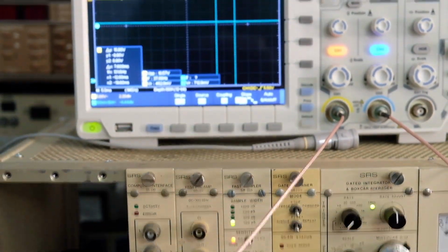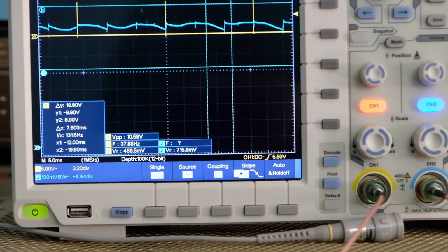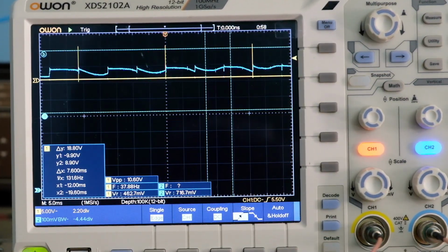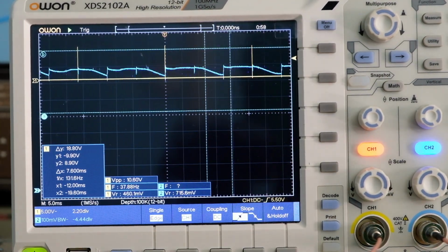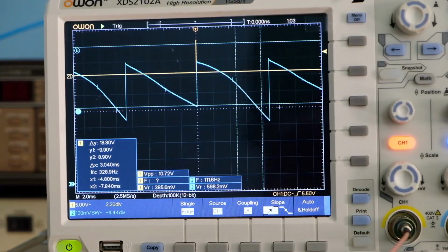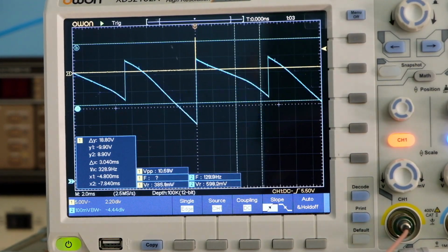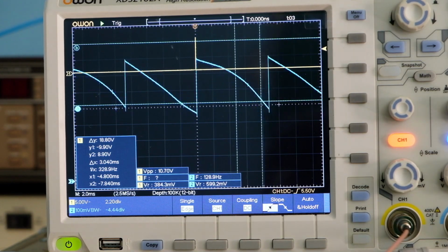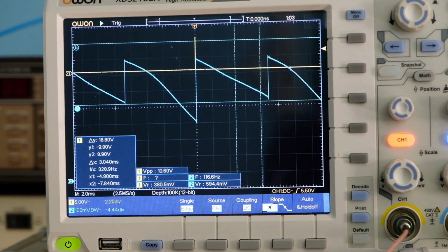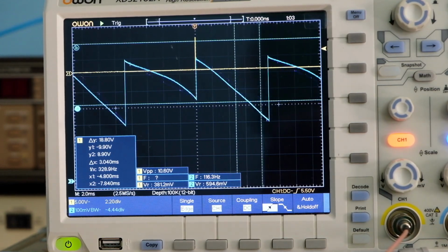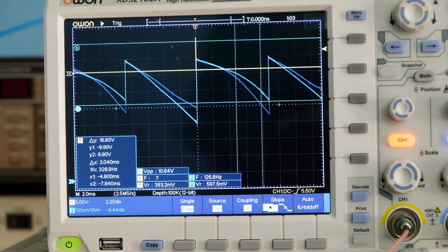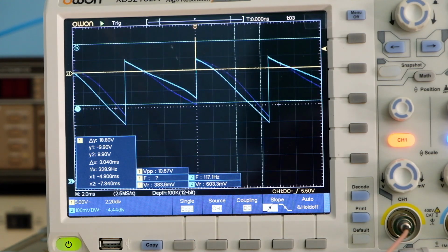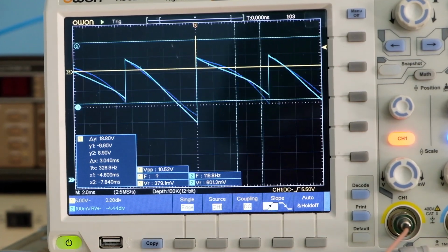As you can see right now, it's hard to see on this scale, but it's actually right before the reset occurs on this particular display here. So back to the zoomed out view, you can see how much variation there is on every cycle of this trigger that's going on. And so you can see that the boxcar integrator is an extremely useful tool to measure these kind of repetitive signals which are corrupted by environmental noise on the actual signal you want to measure.